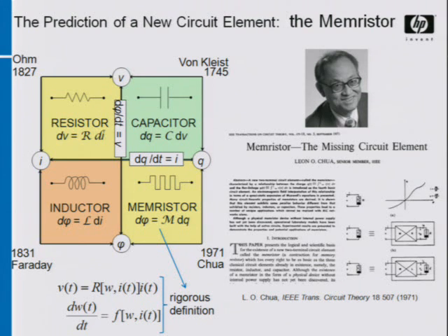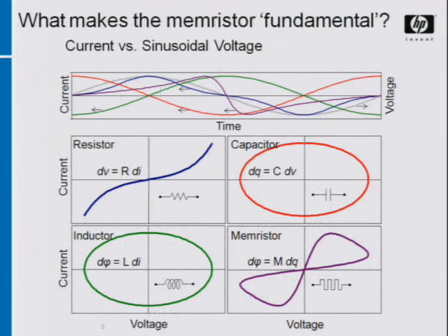And so if you have a memristor and you wish to understand what its devices are, you must figure out this equation. You must understand what W, the state variable, is as a function of time. And once you have that, you can predict every property that you need to know about the device. So, what's the deal? Well, the deal is, as Leon said, the memristor has a pinched hysteresis loop. All right, whatever that means.